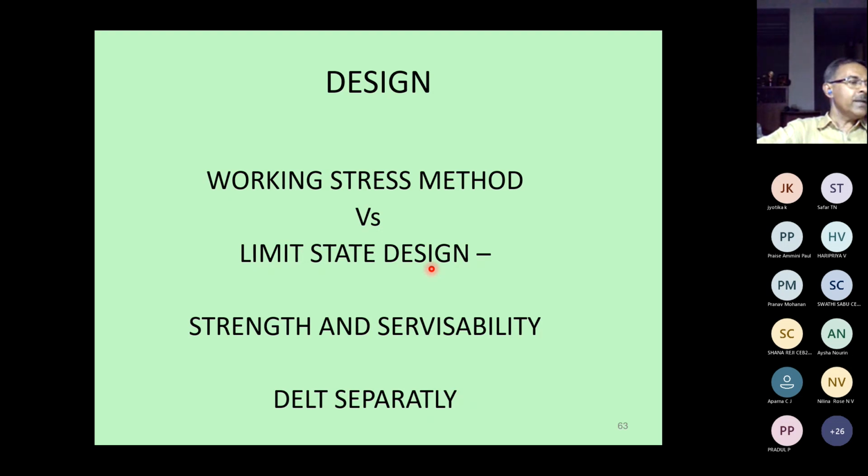So in the limit state design, we divide strength and serviceability into two parts and deal with them separately. The serviceability is not given much importance in the working stress design. We take a presumption that by limiting the material stress, our serviceability is automatically satisfied. But in the limit state design, both strength and serviceability are to be dealt with separately.